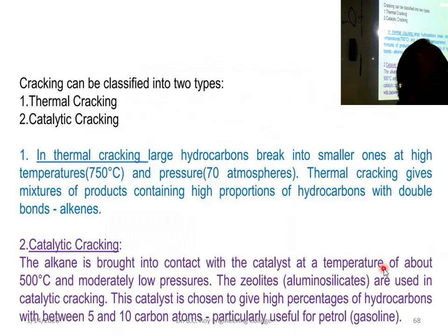So when you are making 2 gram or 10 gram, and when you are making 2 ton, there is a hell and heaven difference. Why? Because in this case, you can mix it by your hand or by a stirrer, and when you are taking 2 tons, how do you mix it? By some motor. It may not be sufficient. Then what will happen? The outside peripheral area is not properly stirred, the central area is stirred.